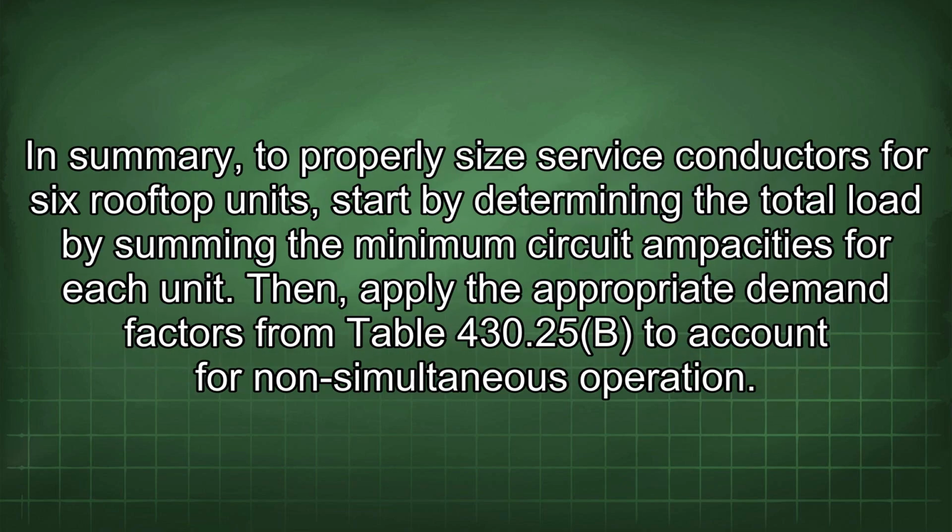In summary, to properly size service conductors for 6 rooftop units, start by determining the total load by summing the minimum circuit ampacities for each unit. Then apply the appropriate demand factors from Table 430.25b to account for non-simultaneous operation.